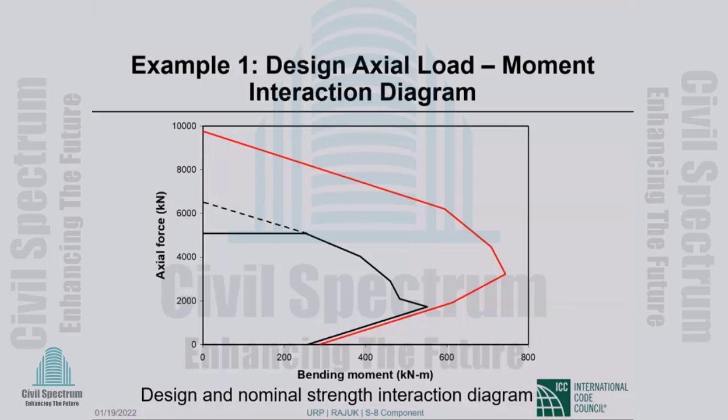Well, it is sometimes required, not all the time, but if you have a seismic situation, which is much of Dhaka, you have a column supporting a discontinued shear wall. The column ties have to continue at least 12 inches into the support. So there are cases where you are required to continue the column ties into the foundation.